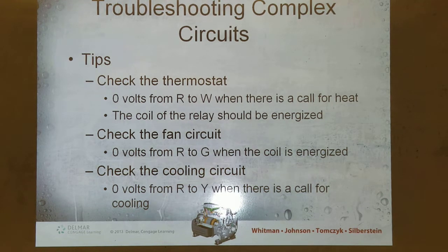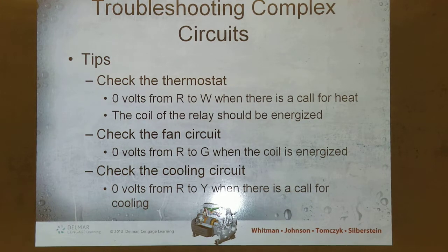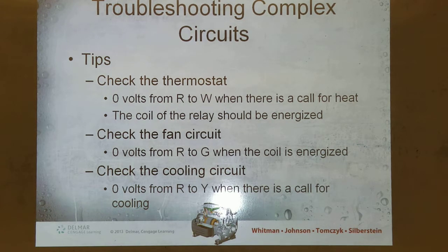Okay, so what they're talking about is these 4 terminals right here. Hot, cold, fan, heat. That's when they're saying R to G, R to W, or R to Y, right? So you're gonna check voltage between those terminals. What should you get between those terminals? What kind of voltage? 0. Oh, yeah, 0. Makes sense.